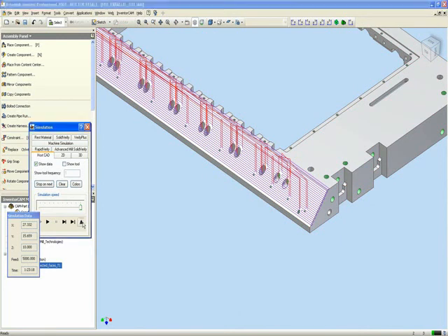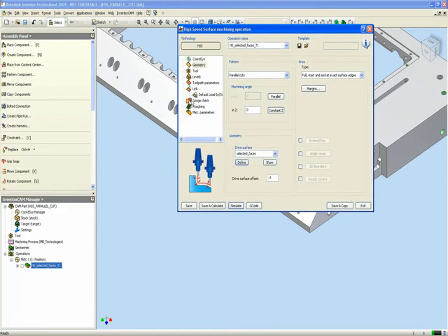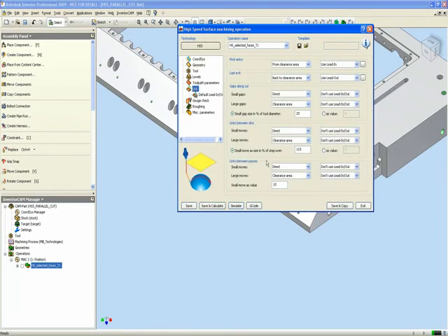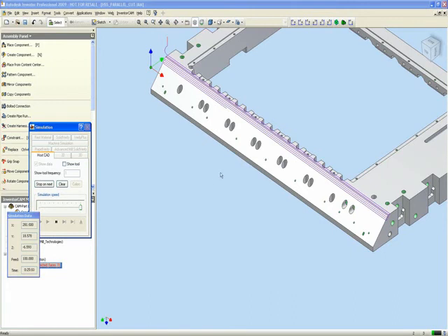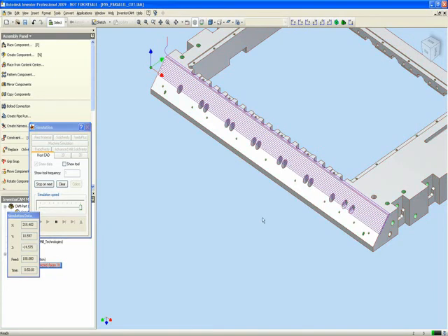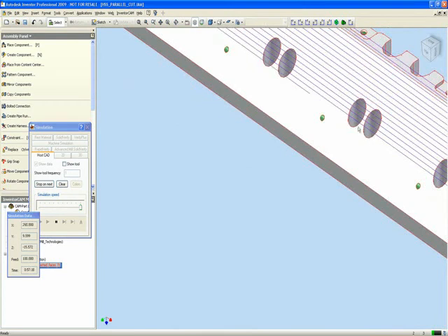For that, all I have to do is go into my links and change my gaps along from the large gaps also to direct. That way the tool will go directly to the next area. You can see in the simulation now that the tool pass will jump over these areas from one surface directly to the next surface as shown here, without jumping up over the surface itself.